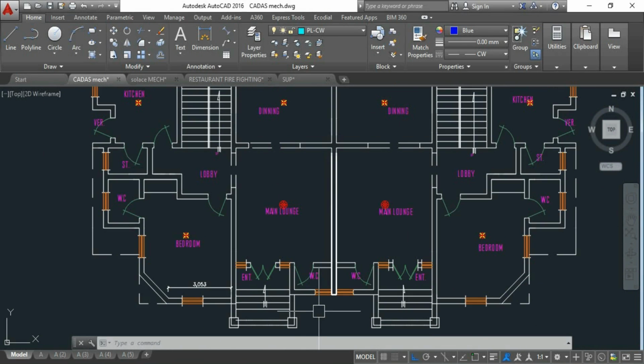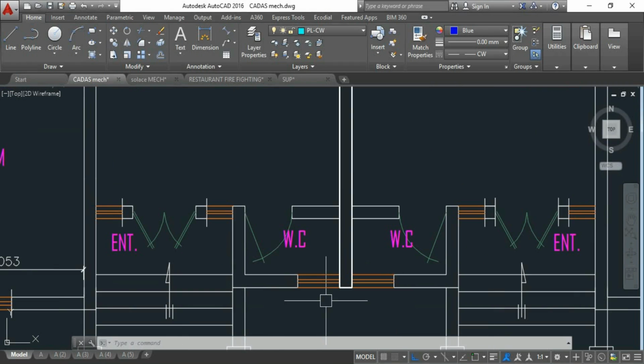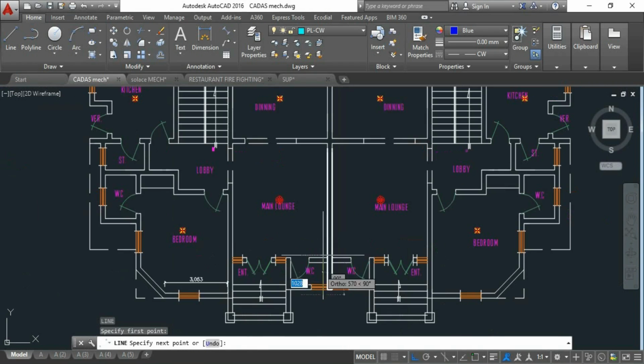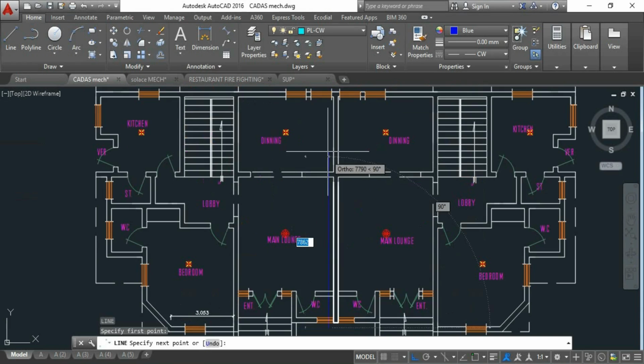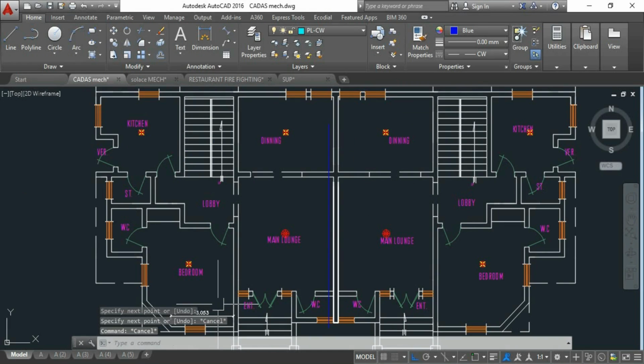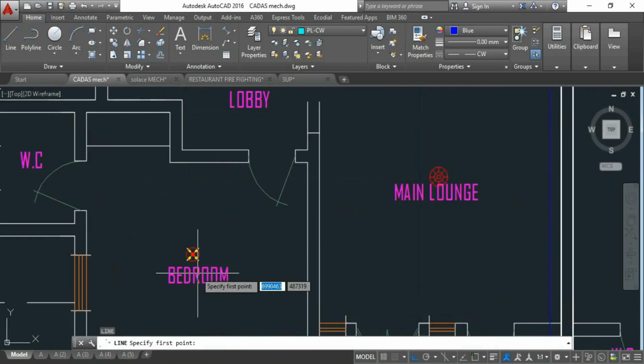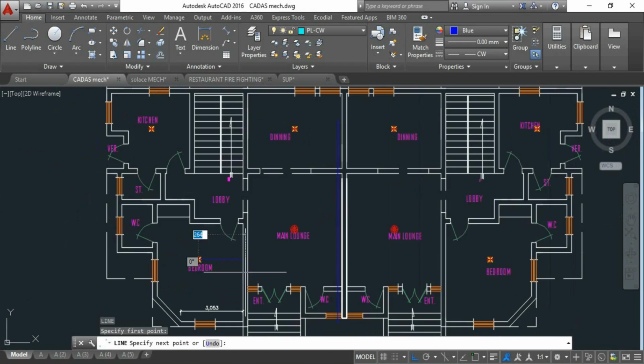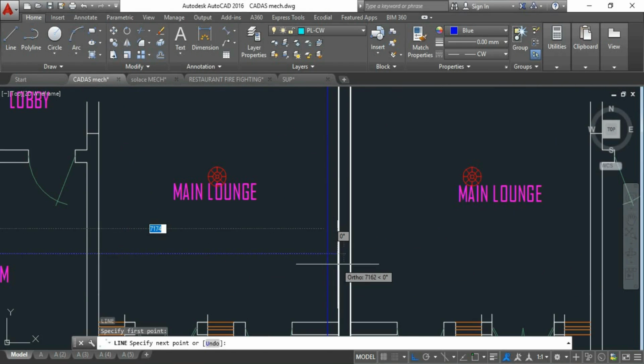The next process is to define the simplest connection that will reduce the material usage. So let's just use an ordinary line first. Probably our mains is coming from this end. Mains always prefer going straight, so let's assume going straight for the connection. So for this connection, we'll be having our mains like this. So we now start dividing our pipes. So we have a sprinkler here. This sprinkler must be connected to our mains. Let's assume it's connected here.